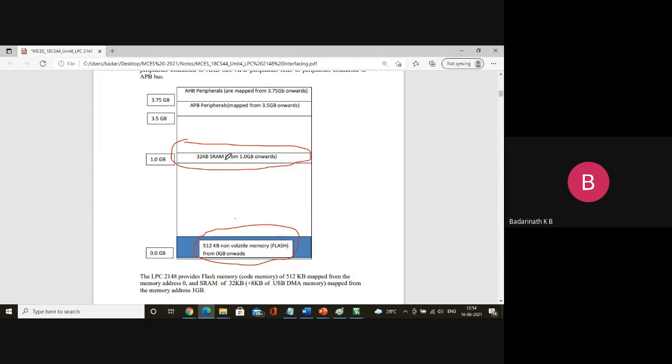So these different programmable registers, which are provided outside the core but inside the microcontroller, are used to configure the working of different blocks. How do you access them? Since they are present outside the core, you should provide an address to access each register. These addresses are provided as a part of the total 4 GB, as a part of the memory space itself.